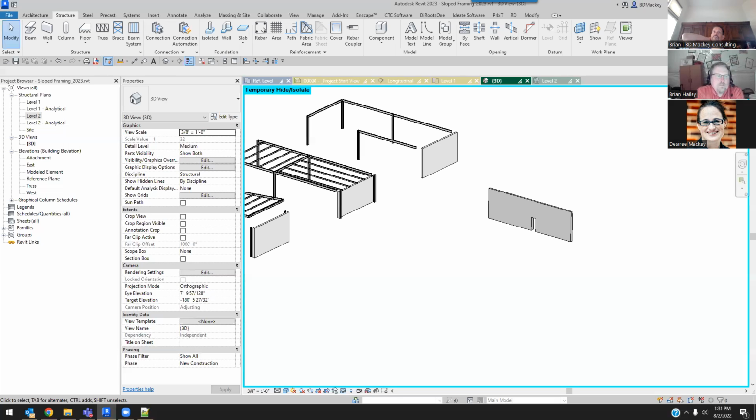Yeah, and the registered applications aren't in the normal purge command either. You have to do the -purge to get to it. -pu, you have to do the command line version of purge. And then you'll get the option for registered, -pu. Exactly, Jason. So yeah, that's one I would try, but 90% of the time, it doesn't surprise me you're having issues with this CAD file being linked in. I mean, it's Revit, it doesn't play well with CAD stuff.